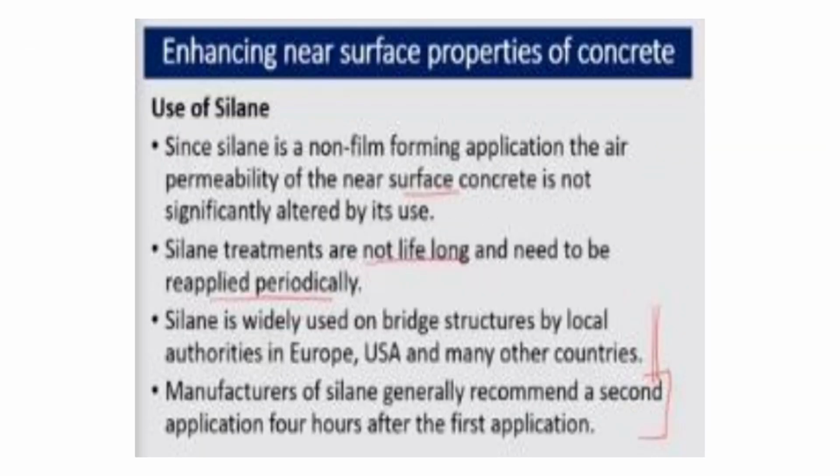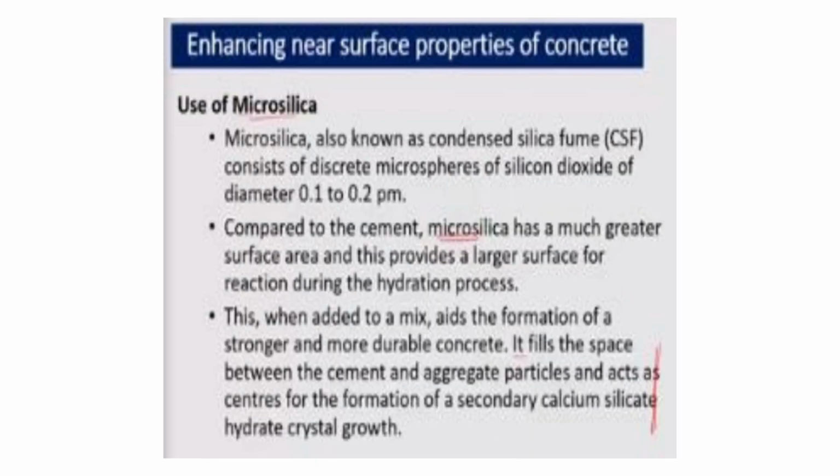The silane treatments are not lifelong, however, and need to be reapplied periodically. It is widely used on bridge structures by local authorities in Europe, USA, and many other countries. The manufacturers of silane generally recommend a second application 4 hours after the first application. So these are some of the guidelines and requirements which are needed for the use of silane.